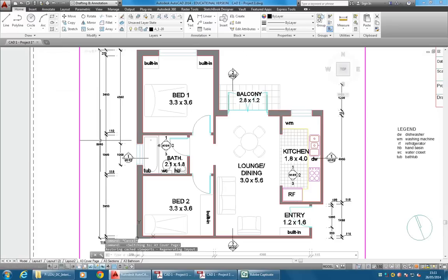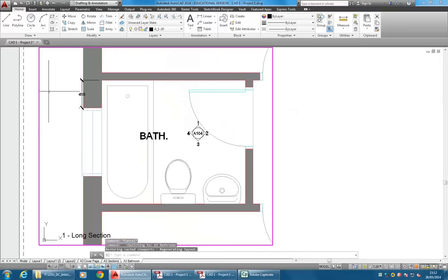But when you go to the viewport on your page that's set up for a certain scale, it knows to turn the other ones off. So here, that 1 to 20 dimension that I drew, measuring that little part there, it's gone. All these other dimensions are on. On the bathroom plan, you can see all those other dimensions are off, but this one's on. Okay, so the whole point of the Annotated is to help you manage your scales.